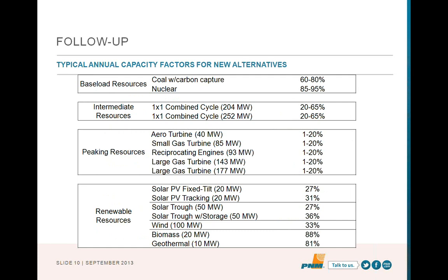Say with our reserve margin tolerance, we could add, say, 100 megawatts more of capacity. So Strategist will build a portfolio that has, say, 2 40-megawatt plants. It'll build a portfolio that has this reciprocating engine option. It'll build a portfolio that has a small gas turbine. And it'll build a portfolio that has nothing also, if we're above the reserve margin tolerance. So it'll create, in my example, 4 portfolios. Then it'll move on to the next year, and it'll do that every year. So you can think through the different combinations and permutations of that. That's how you end up with thousands of portfolios.